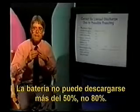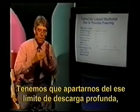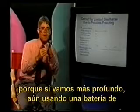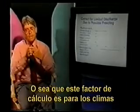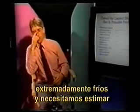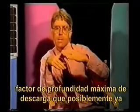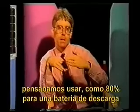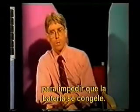The battery can't be discharged more than about 50%, not 80%. We've got to back away from that deep discharge limit, because if we went deeper, even using a deep discharging battery, the electrolyte would freeze. So this calculation factor is for those climates that are extremely cold, and we need to correctly estimate how cold the battery will get, back away from our maximum depth of discharge factor that we may have already been planning on using, like 80% for a deep discharging battery, and use only that amount that is safe to prevent the battery from freezing.